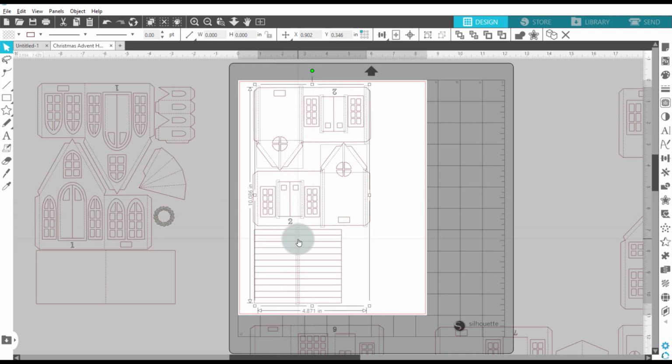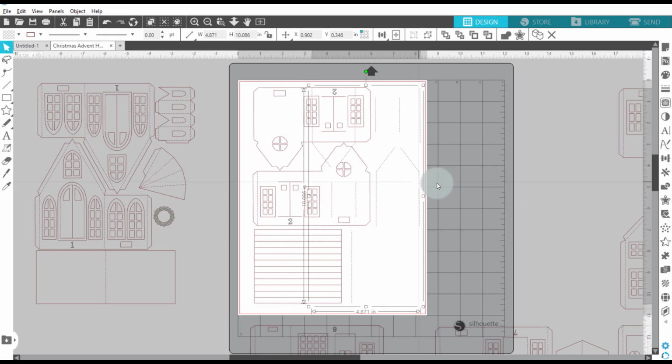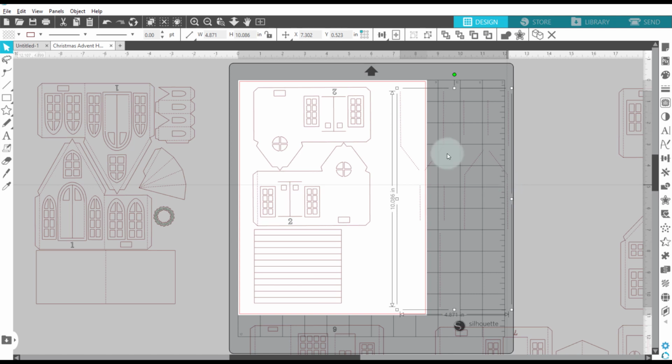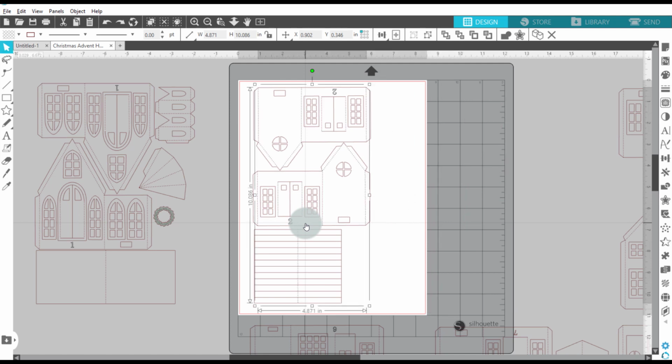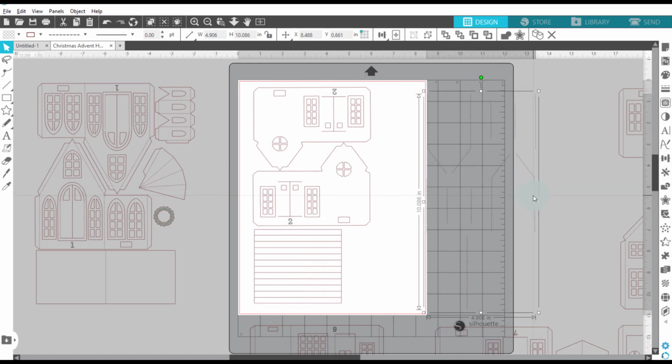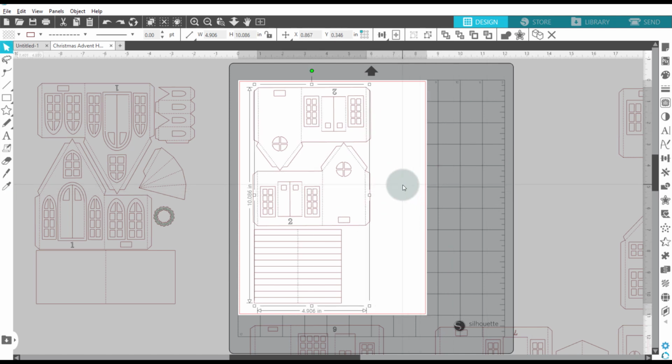And then this one down here in the middle. And we're going to Control G. And then we're going to drag them off to make sure that we got everything. And now look, see, we missed this score line. And this is why it's important to do this. So hit Control Z, which puts them back into place. Hold your shift key down and add that score line. Hit Control G again. And now we've got them all together. That's why it's so important to move them off, just to make sure that you've gotten it right. Hit Control Z, they'll go back into place.